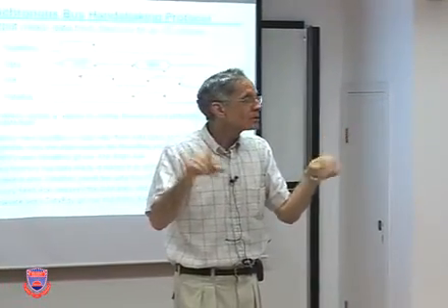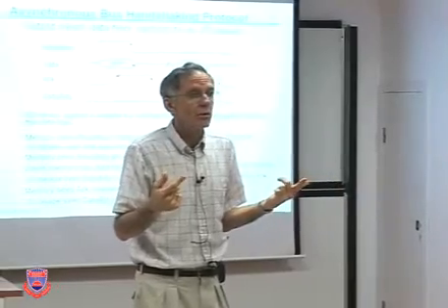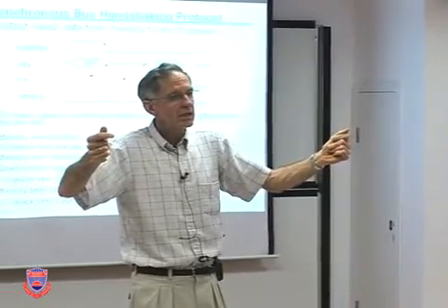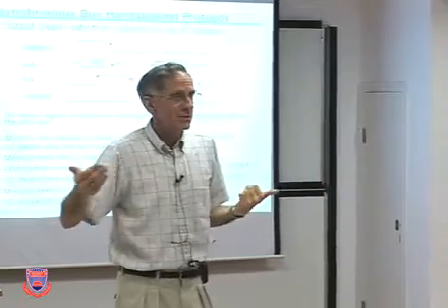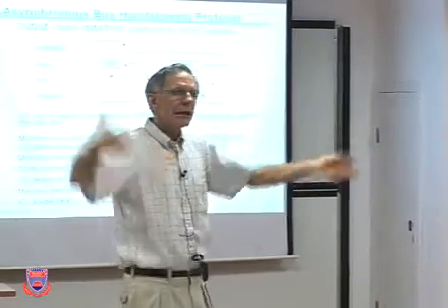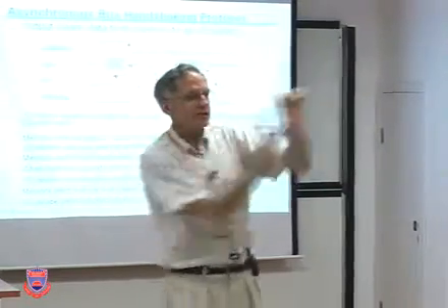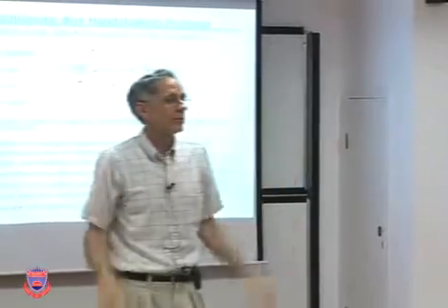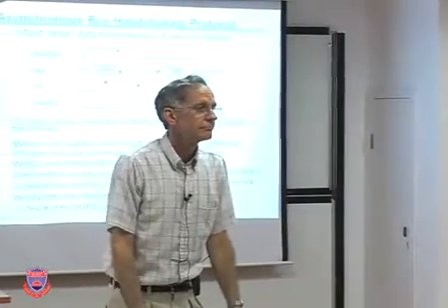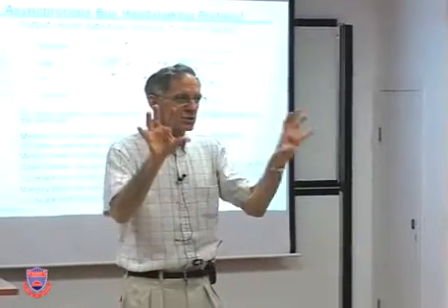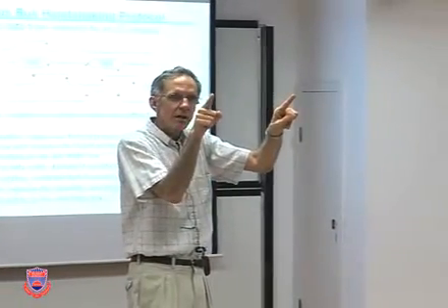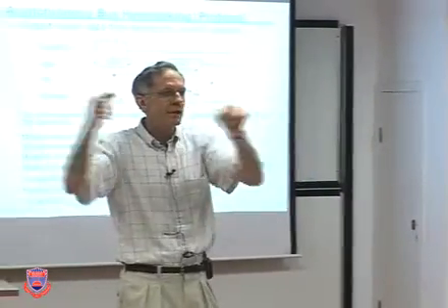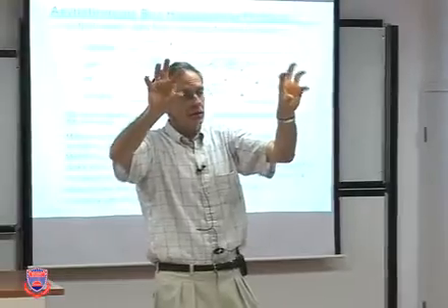And as you know, state machines can be designed to run synchronously on clock changes, or they can be designed to run asynchronously on input level changes. So you can make these state machines clocked internally in device A and device B, or unclocked if you want. Okay? Doesn't matter. Anyway, the idea is there are 2 state machines. So once we start into the sequence of changes, unless there's something that says go back home, we're going to finish it and get back to the starting state again.